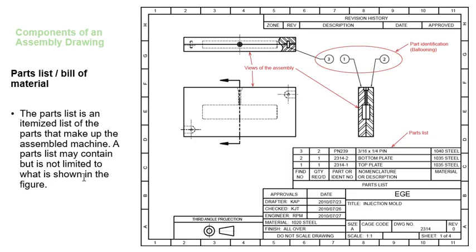Alright, so let's see how we're going to do all of that. So here's a big picture and here's a drawing. Everything else is the same right there, and the only thing that's new is your assembly right here, and then here is your parts list. So when we identify the part, we put the little number right there, balloon it or circle it, and then give a leader line and show what the part is that you're identifying. So here part number 1 is this one, part number 2 is this one, and then part number 3 is that one over there. And of course, these are the views, 1, 2, 3 views that we're using for the entire assembly. Okay? Not that bad, right?